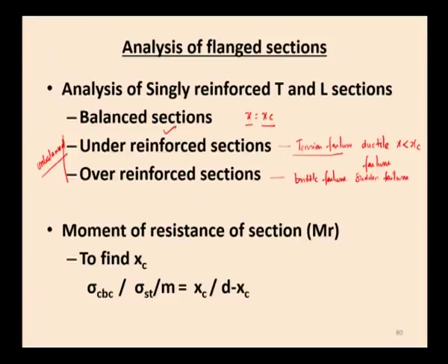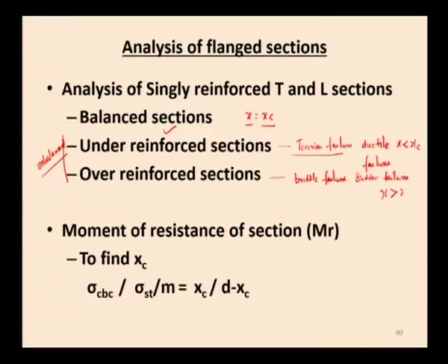But in the case of an over-reinforced section, here we are using more steel, so automatically the concrete area will be less. So, the neutral axis moves towards the bottom. Here, x is greater than xc, that is the neutral axis position of the unbalanced as well as